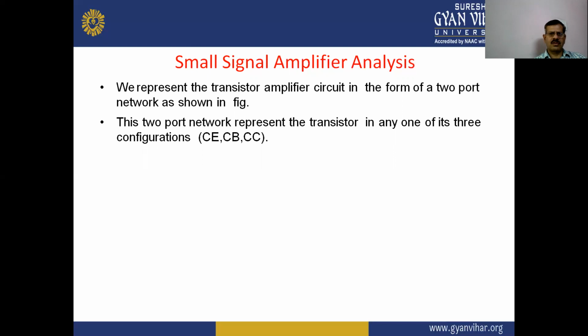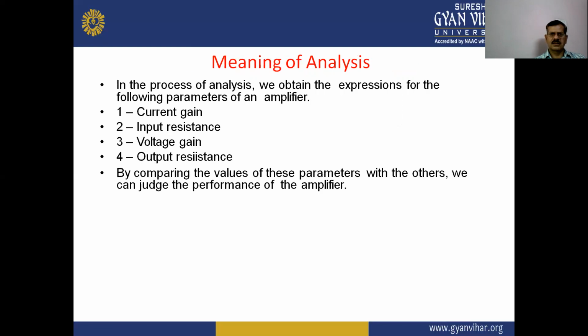Now next one is small signal amplifier analysis. So we represent the transistor amplifier circuit in the form of a two-port network, and this two-port network represents the transistor in any one of its three configurations: common emitter, common base, and common collector. So what is the meaning of analysis?